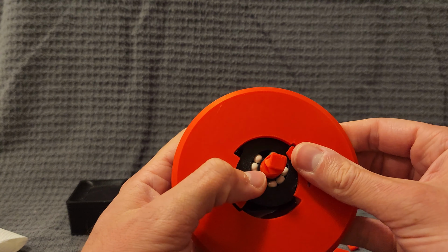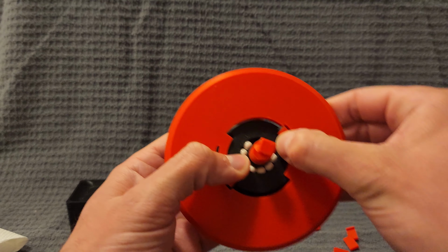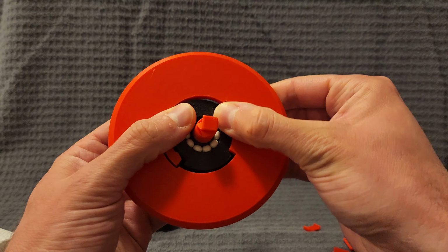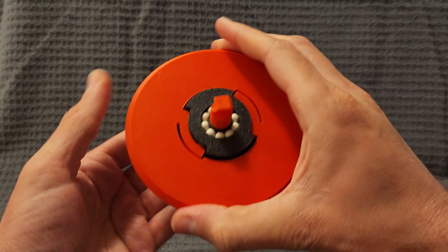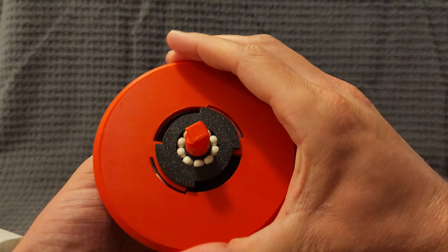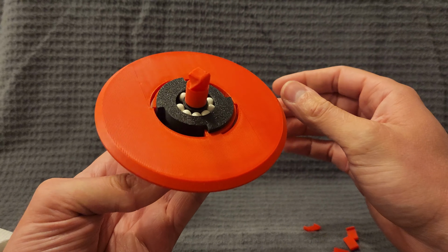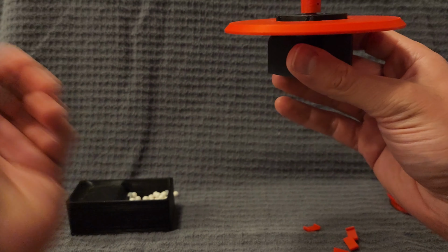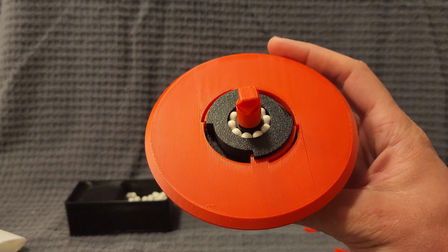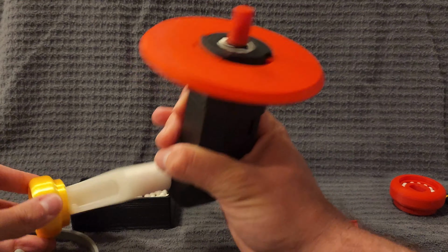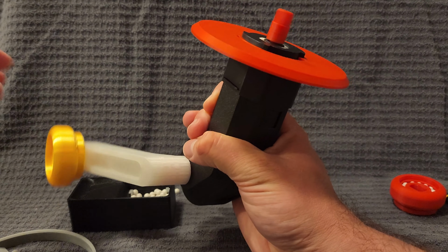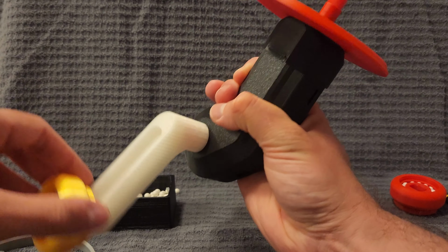Now this is the insertion of the ground effect plate. You gotta pry open the two spring tabs a little bit, make sure you don't break them. Press all the way down, and then you can rotate about 90 degrees for it to lock in place. So it's a really quick mount and dismount design. And yeah, once you're done doing all of this, just push in the handle and make sure it spins smoothly.